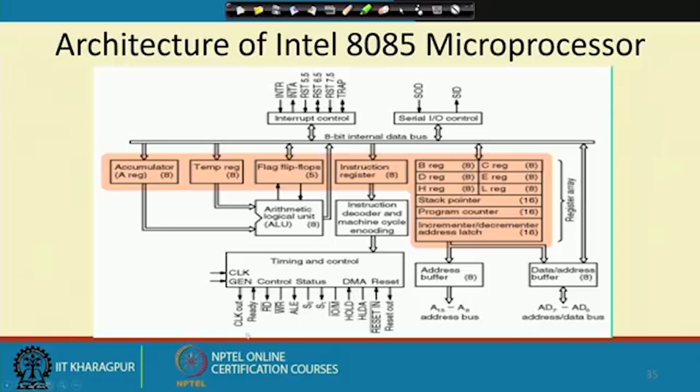then after the processor has put the address onto the address line, it will expect the data to be available after some time. If the memory is not able to give the data within that time, it should tell the processor that it needs the address for some more time. In that case, it will put this ready signal high, telling that the memory is not yet ready and the data is not yet available. That way, ready comes as input to this timing and control module.